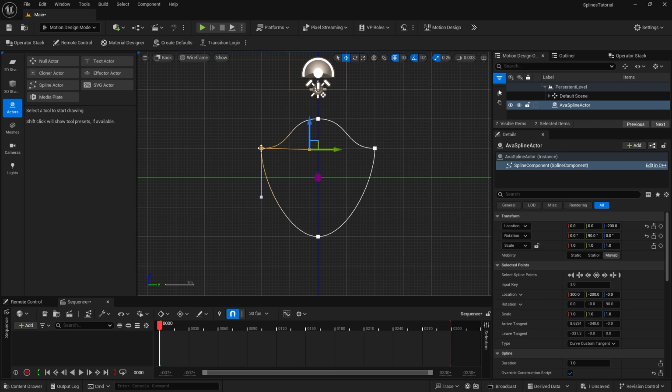Of course, they're going to be slightly different. So this one right here, let me drag it around, and you can notice that on the X and Y there, those positions are changing. And so I'll set that to, let's say, 8.6 right there by a negative 340. And then I'll jump over here and click on this tangent. And I have a negative 8.6. And I need to match it up right there to a negative 340. And so now I know that those are symmetrical in shape.